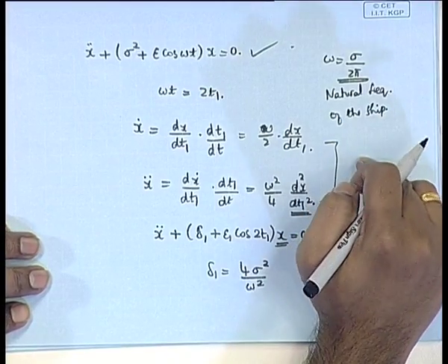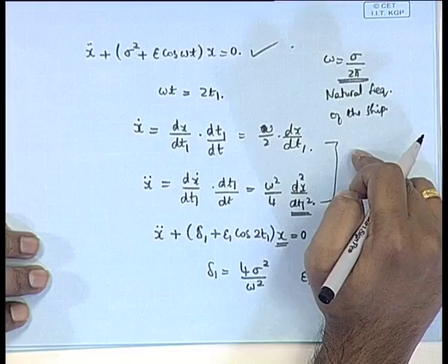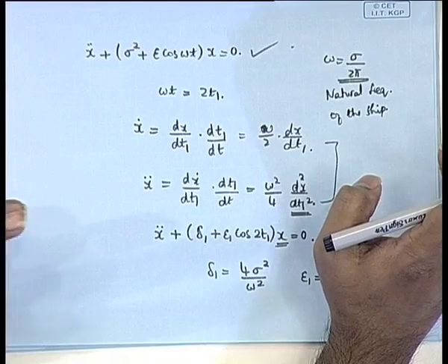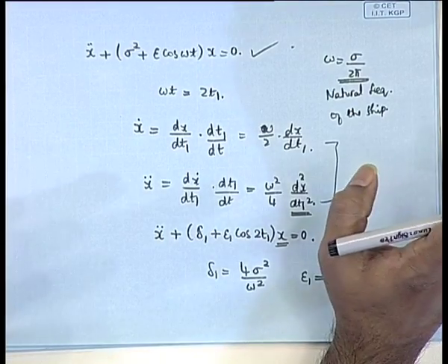This we have already given an expression for. Remember, in some class before, we have given an expression for the natural frequency of the ship. There are different frequencies, there can be pitch, there can be heel, there can be yaw, different kinds of things, but we are talking about the natural frequency of heel for a ship. It depends upon GM, it depends upon I, that is the radius of gyration, and so some root of I by GM, something like that, gives an expression for omega.